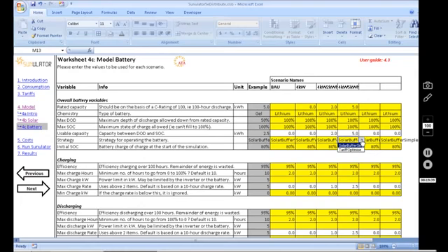The Solar Buffer Simple works on a logic of, if you're generating more electricity than what you're using in the house or the business, then you've got excess electricity. We don't want to just export that out to the grid because normally you don't get much benefit for that. So we're going to charge up the battery instead.